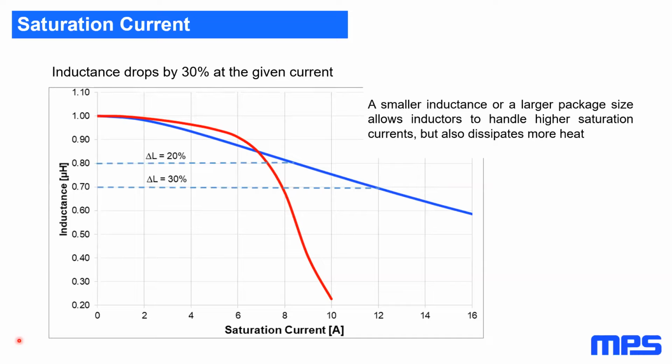So the first one came in, I think, when you were going through core loss, and that question was, which losses dominate inductor losses, DCR or ACR? Okay, regarding losses, I think it was actually back on the hysteresis losses, maybe two slides before. I think it's related to the DCR, ACR. Actually, it's more related to which are higher, the copper losses. The copper losses are two kinds of losses: we have the DC losses and the AC losses. DC losses are the more dominating part of the copper losses.